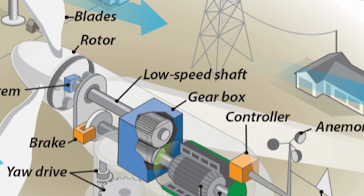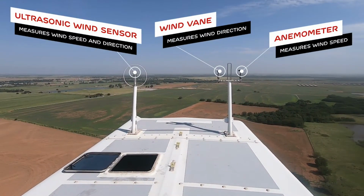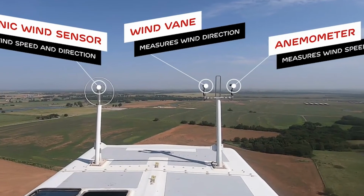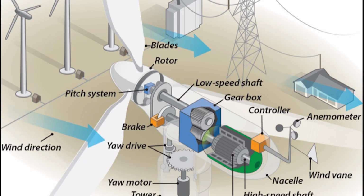wind direction is stable. The system is based on automatic signals from a wind direction sensor called an anemometer, which sits atop the nacelle. It measures the wind speed and direction and transmits the data to a controller. The controller, in addition to rotor orientation, is also responsible for starting the machine at a cut-in wind speed and shutting off the machine at dangerously high speeds to prevent turbine damage.